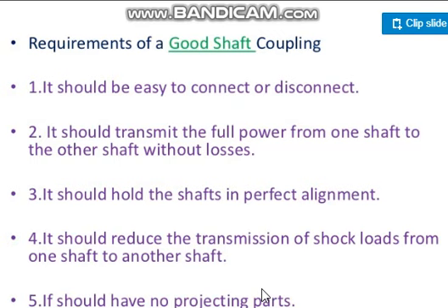That is the reason why the protected flanged coupling is used, because flanges have nuts and bolts rotating at high speed. If you come anywhere close, even if you put a hand, it may hit you with so much force that a wound will be created, or some flying thing. That's why in companies you are not allowed to wear full sleeves or any loose parts of garments. It is avoided. You should not wear it.